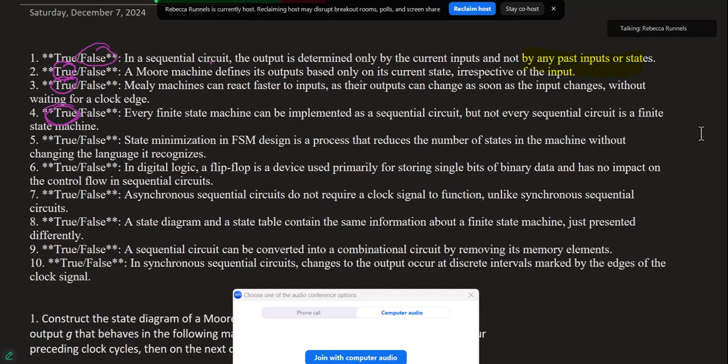Use the state table. Use the state table to come up with your Karnaugh maps, and then from the Karnaugh maps you get the expressions. Given any state table, you can come up with a sequential circuit. It might be quite complicated, and a lot of times you're better off letting Verilog or something like that come up with it for you. But you can do it.